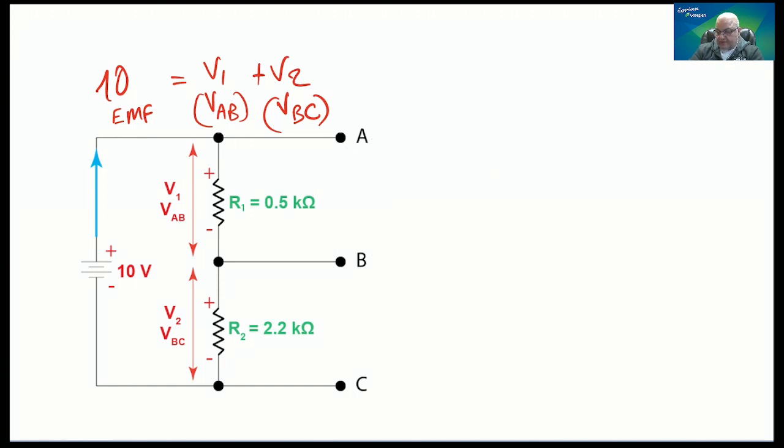how are we using this? I'm going to call it a technique because it is a simplification of rules. So the technique goes like this. V1, which is a division, right? Voltage divider, it's a division, is going to be equal to a certain dividing ratio multiplied by the voltage supply. Voltage supply is going to be the voltage that is across the two resistors we're working on.